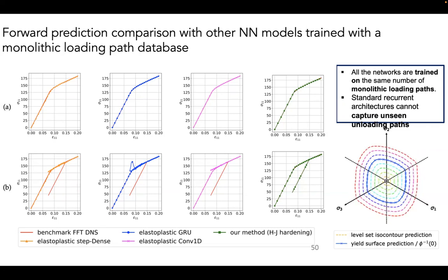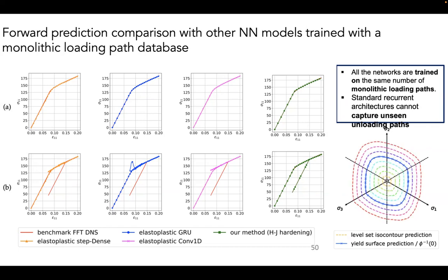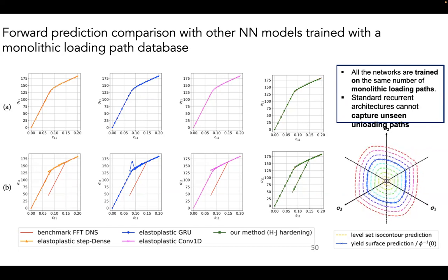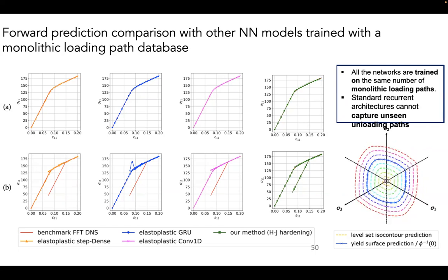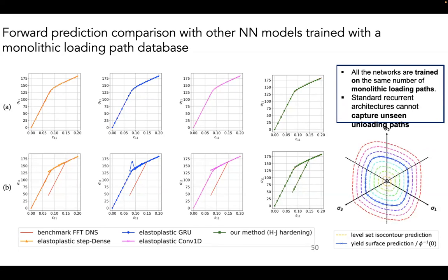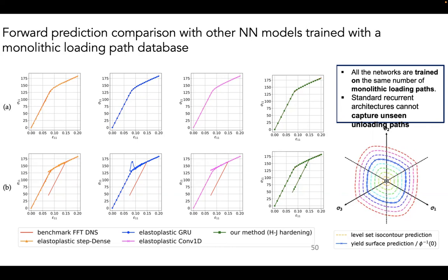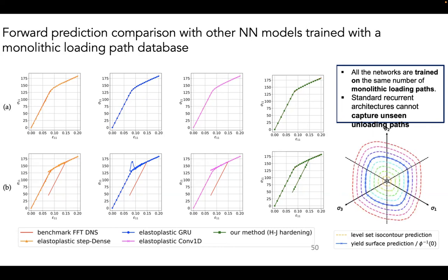Versus if I were using a recurrent neural network, it would be very difficult to do. And convexity is one of the easy tricks to enforce thermodynamic consistency. You don't want to create negative plastic dissipation; when you have energy dissipation, you don't want to gain energy. And that geometric trick is so simple that you can just force the yield surface to be convex, and that's it. That's the end of the story. You don't need to do any post-processing or funny business, or partition the elastic and plastic parts in a post-processing step.